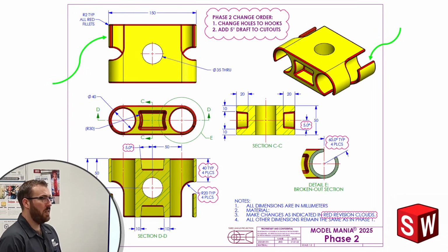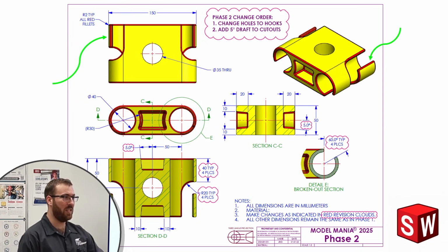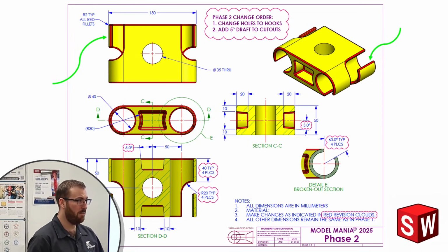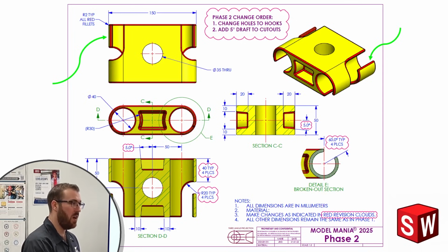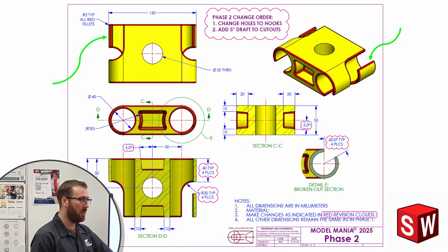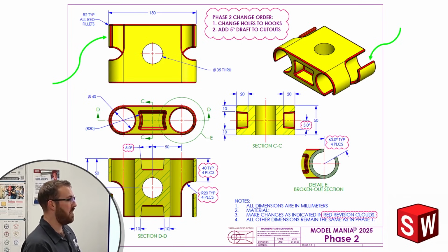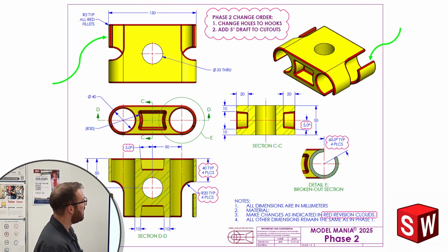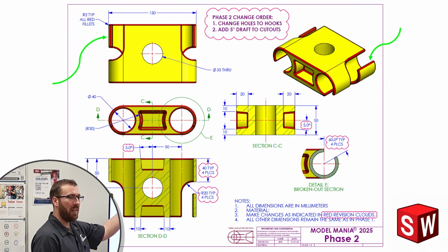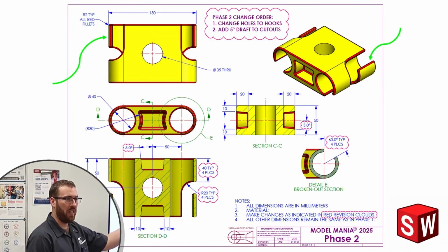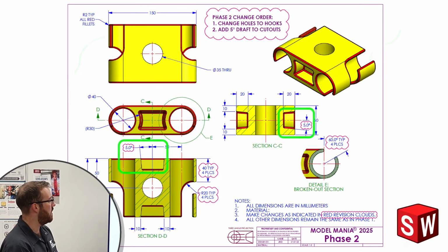First thing I notice, the fillets. We just added those, but they're going to be in the way. You do not want to cut into existing fillets. You always want to save fillet features for last as long as they're cosmetic, which all these highlighted red ones typically are going to be. There is a fillet feature here that is not cosmetic. We'll get to that shortly. But we're going to have to roll back to get those out of the way. We don't want to try to cut through those and fix them later. So that's the first thing that stands out.